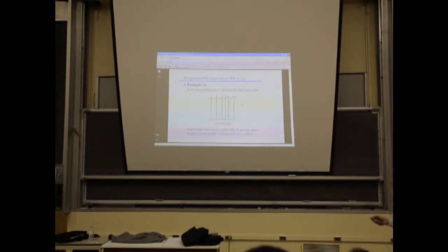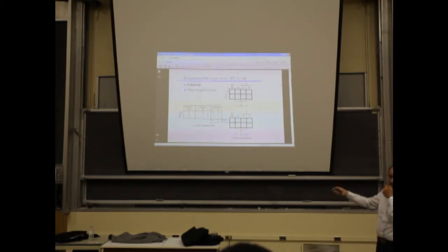Yes. So we have a function here given to us. This could be an exam question where you are asked to program a PLA. This is the one that has both AND and OR programmable, okay? So this is the function. You go and do the Karnaugh map. You create the different product terms. So I did the Karnaugh map here, and that gave me the expression for the first one and the expression for the second one. So now I determine the product terms that I need to program into the PLA, okay?